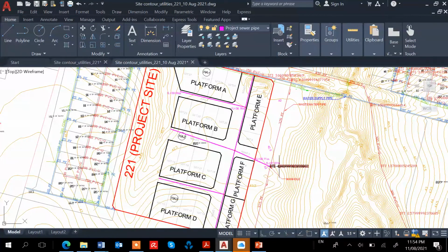So it's quite steep. Compare it to the other line that we need to determine later on, the stormwater pipe. The drop in slope of the stormwater pipe is much smaller. Compared to the sewer line, for the stormwater pipe we can go to about 1 in 300, meaning one vertical and 300 horizontal.